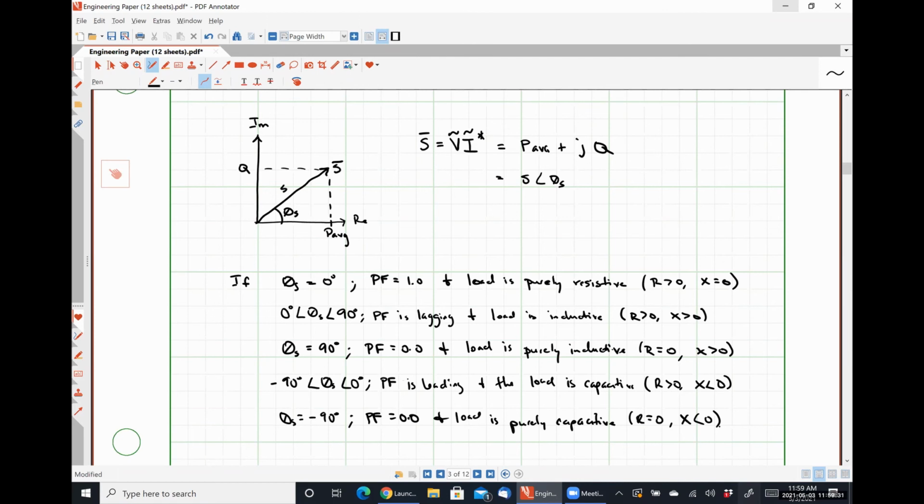The resistances that we're dealing with in that class are typically on the order for metals and things like that, a sheet resistance of about 100 milliohms per square or smaller, depending on whether it's the metal 1 layer, metal 2 layer, metal 3 layer. The thicker it is, the smaller the sheet resistance is and all that kind of good stuff.